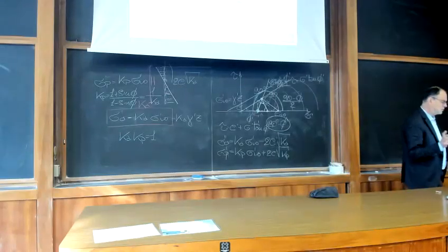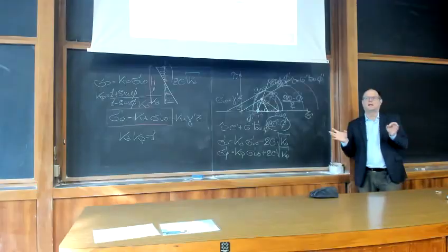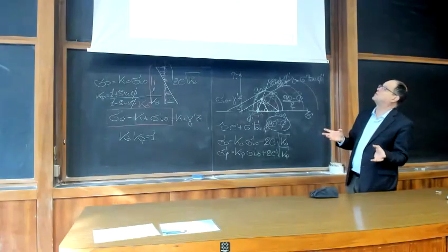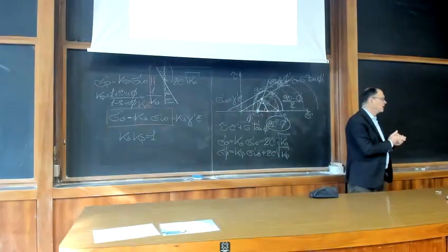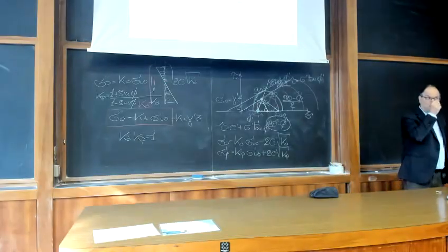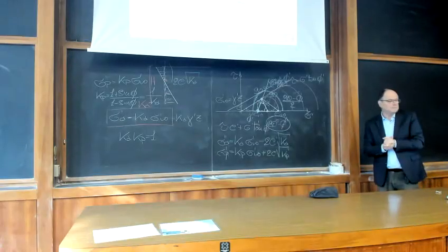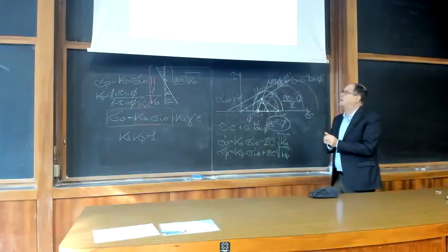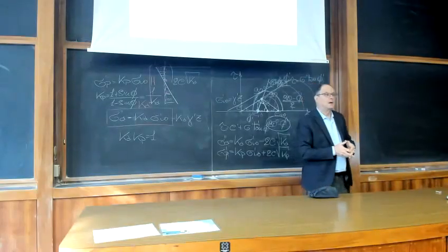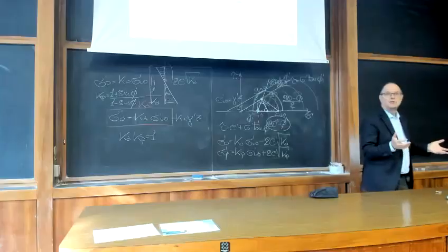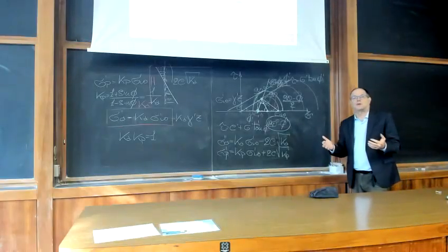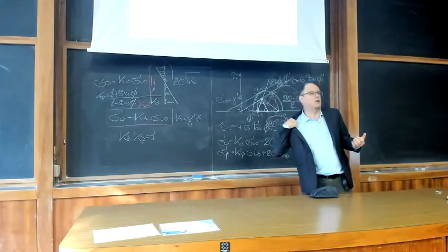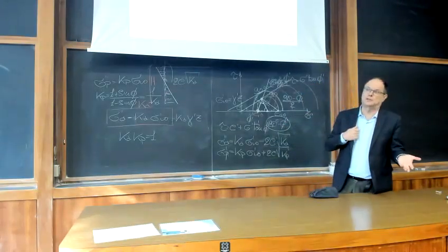We have to understand that you might have essentially two types of foundation, shallow or deep, with a question mark, because you have to decide which is suitable for your structure. Shallow foundations are simpler, are cheaper, are easier to design, so we will typically try to design a shallow foundation. Anytime it is possible to use a shallow foundation, you will go for a shallow foundation.